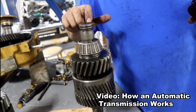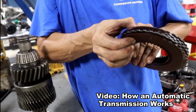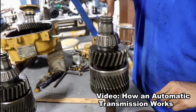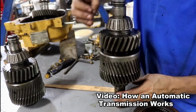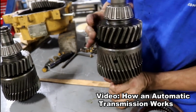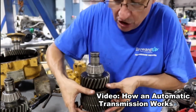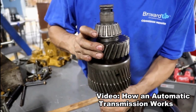When the fluid enters over there at high pressure, the fluid immediately connects both plates, and this shaft with this shaft are connected together. When the fluid enters at high pressure internally, it closes the discs, and the shafts are connected together immediately. At this moment, because I don't have fluid, this shaft rotates free with respect to this. This is the function of the clutch pack. The clutch pack, when the fluid enters and compresses, connects this gear with this gear.